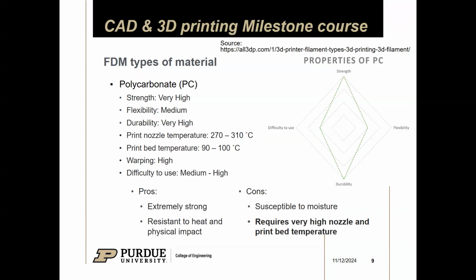Pure polycarbonate is really hard to print. And you need it to be really dry. Again, like nylon, printing out of a heated dry box. Obviously, at these temperatures, you really need an enclosure to prevent warping. But if you want something strong, polycarbonate's great.